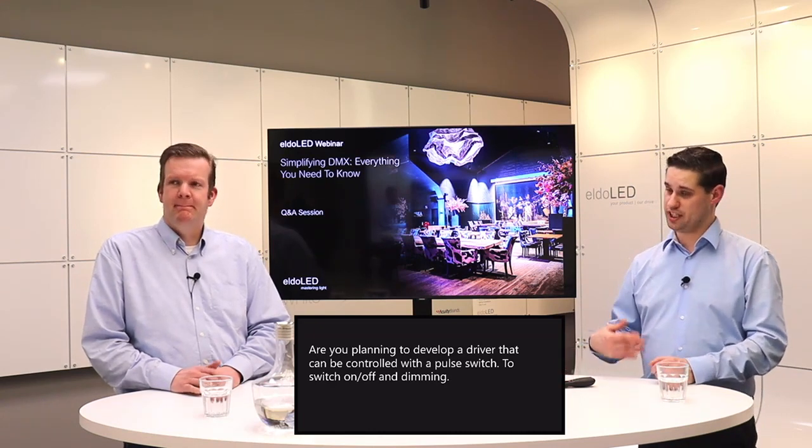Yeah. And what we did in the last 6 months, we launched a lot of products, our existing DALI products, to support pulse dimming. You can see that from that pulse logo on the driver label. Those products are supporting a pulse on the DALI input. So you can use a regular momentary switch having 230 volts on that cable. You put the 230 volts line voltage into the DALI terminal. So line and neutral will be put into DALI positive and negative.